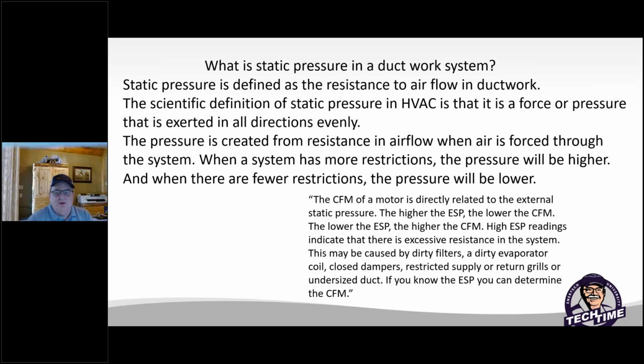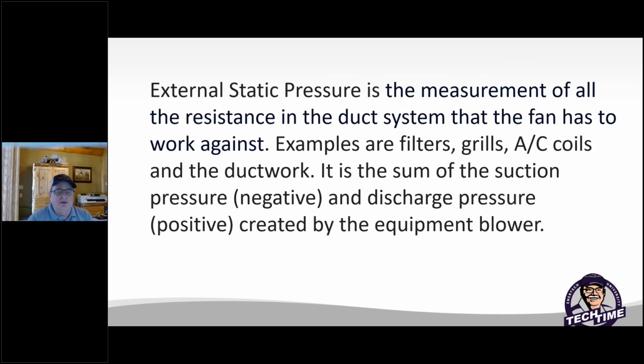External static pressure is a measurement of all resistance of the duct system that the fan has to work against. Again, examples: filters, grilles, AC coils, the ductwork. It is the sum of the suction pressure, the negative, and the discharge pressure, the positive, created by the equipment blower.